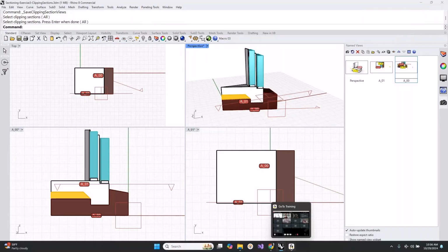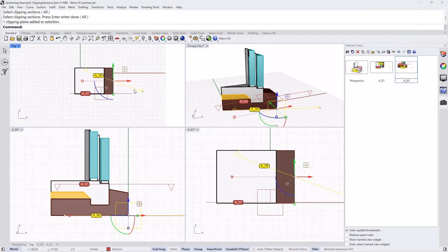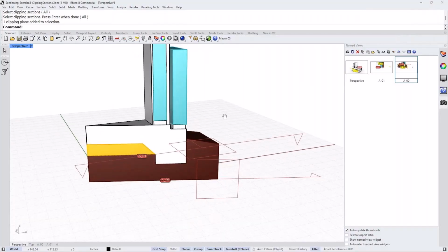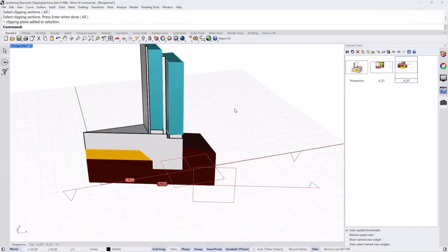You're correct that the visibility is the entire model viewports. When you get into layout and into a detail, you have more options, and one of them is hide in detail. So if you just wanted one of your clipping planes to be hidden in the detail, when we get into the layout, we have that control. But here, all the model viewports are affected at one time. Okay, thanks. No, you're welcome.